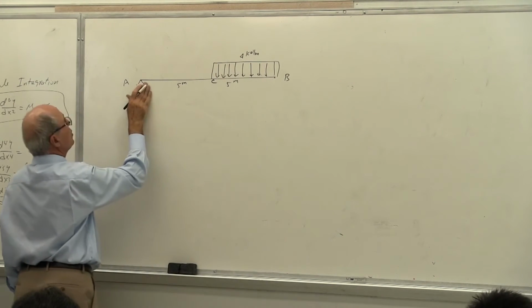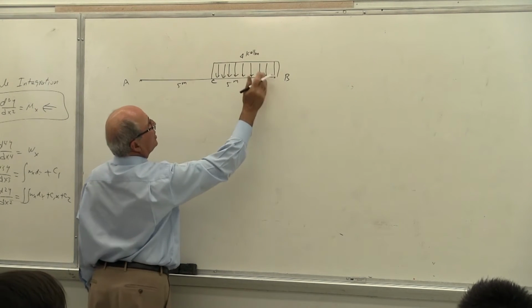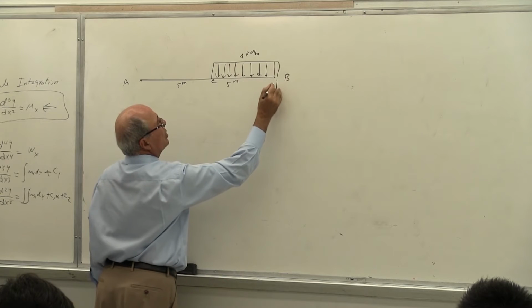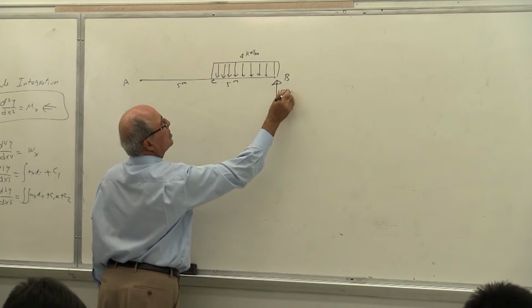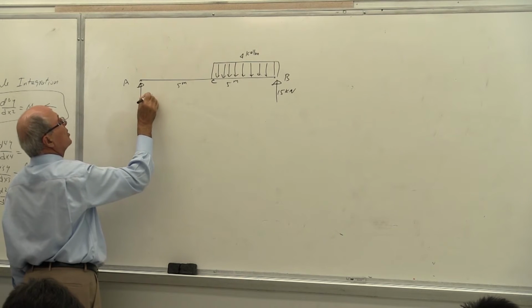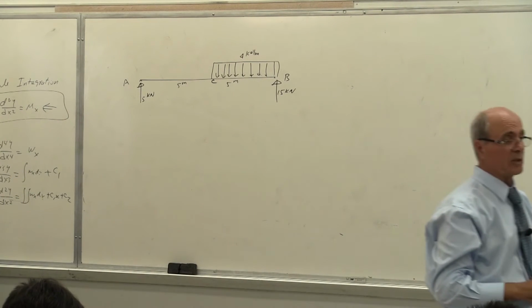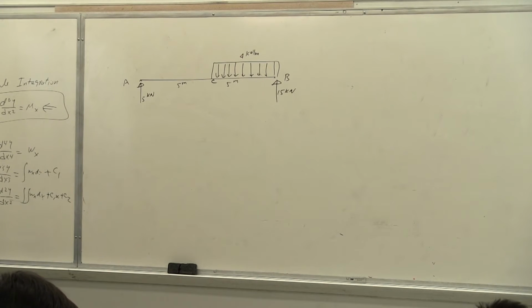I leave that part to you. So the reaction becomes 1/4 here, 3/4 there. So this one becomes equal to 15 kilonewton, the ratio, and this one becomes 5 kilonewton. This is the reaction. This system is determinate, so you can solve the statics of that and get that. Is that correct or not?